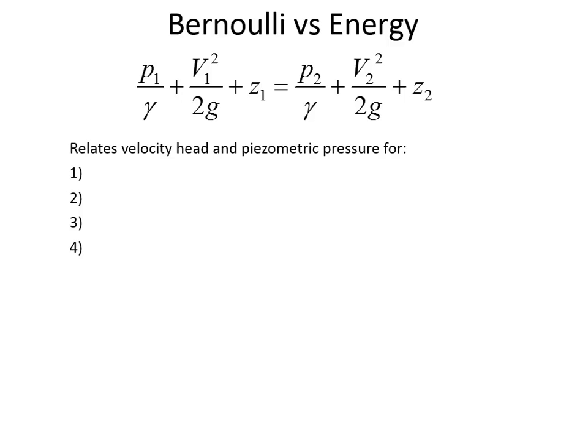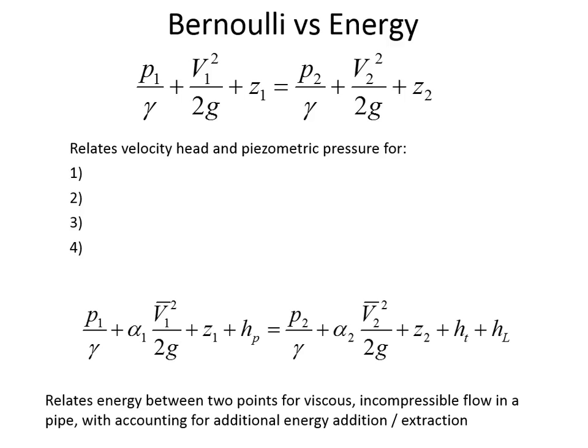But over a really long distance, say the distance from a water tower to your house, there's going to be a lot of friction loss. We're not talking about inches anymore. We may be speaking about miles. And so that steady loss of pressure due to friction of the water and the pipe wall interaction is far more significant. So we have to have an equation that builds on the principles of Bernoulli but accounts for some other things along the way.